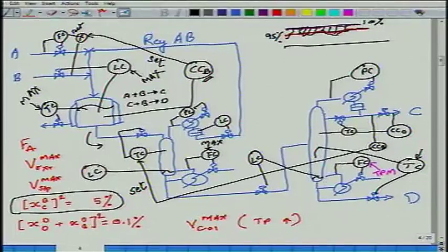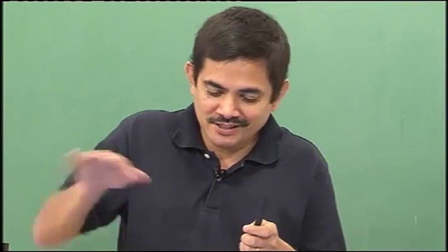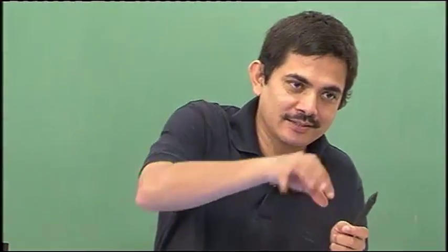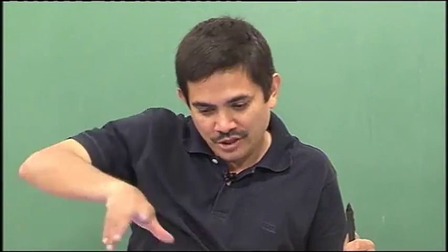Level needs to be controlled. You see, I cannot have level floating, because then if level goes below 20%, I will have to shut down the process. Well, you see, we argued, I do this gets sucked in, that gets sucked in, ultimately more feed is getting sucked in. It has to happen automatically by the way you structured the control system.